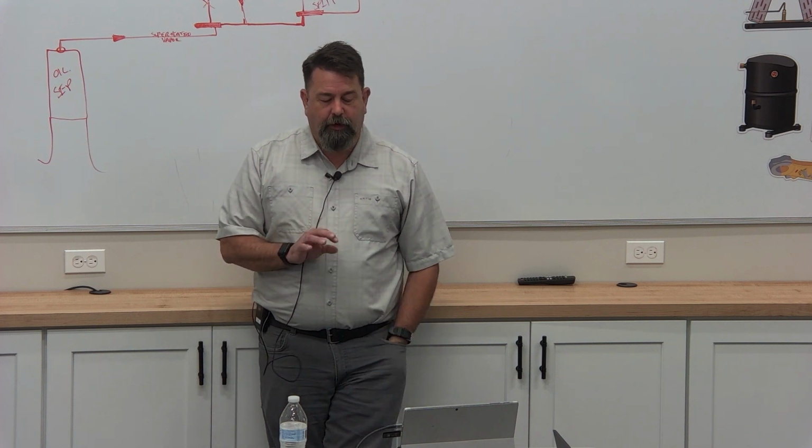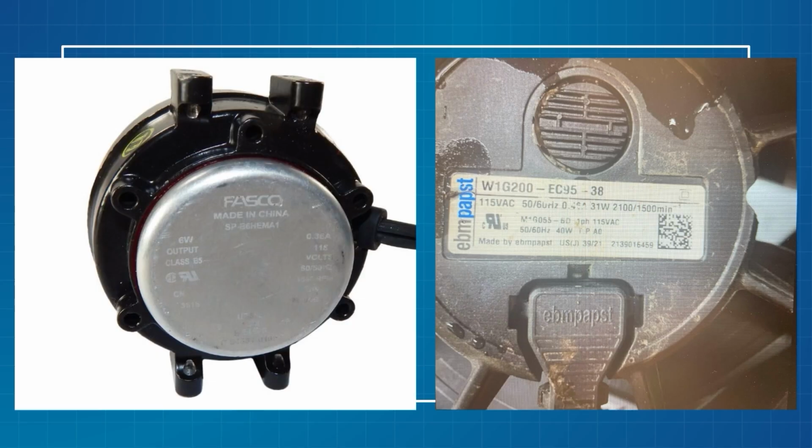It's a valid point to talk about what he just said. In the old days, every technician carried cannonball fan motors. A 3, 4, 6, and a 9 were pretty much standard, and then maybe you'd have a few 12s floating around, right? That covers 95% of your cases. That's just not true today because they're inefficient, right? When I put this cannonball up here, understand when it says it's burning, remember, these are rated in watts, not horsepower.